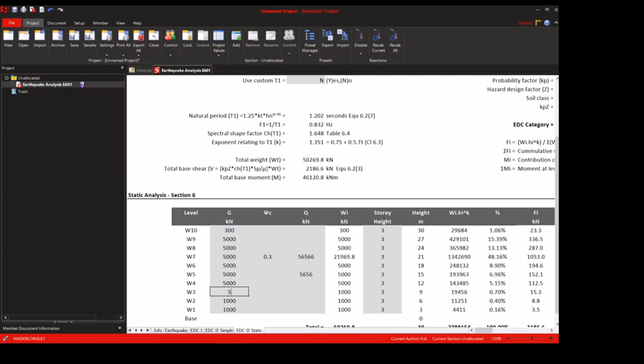And what about the second one? This one is to do with the combination. This is to do with another standard, 1170.0. It depends how important the building is. If the building is residential, then the standard is saying you don't need to assume the building is always 100% packed with people, because, like your house or the room you're sitting in, maybe you are the only one there. And in a bedroom, maybe only 2 people.